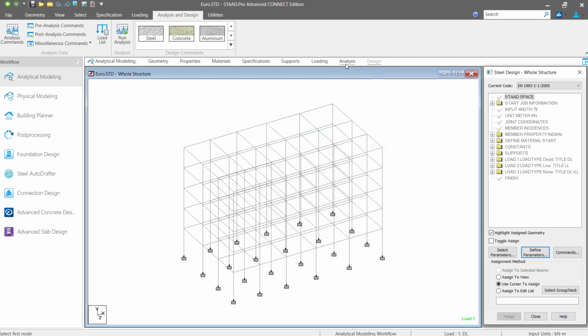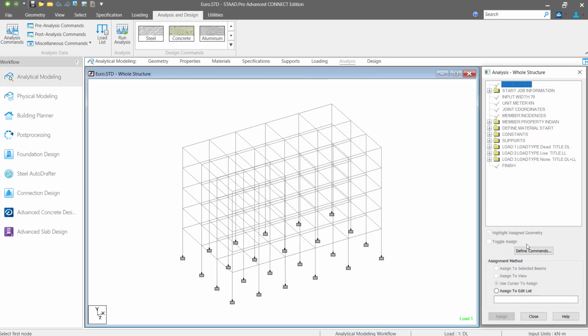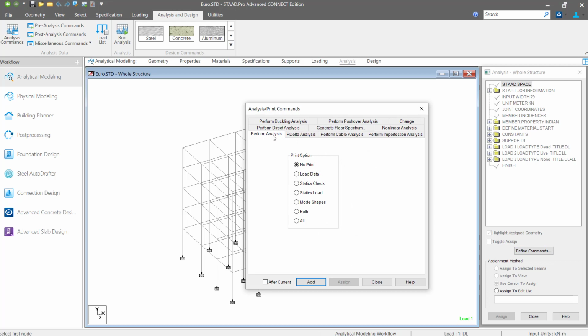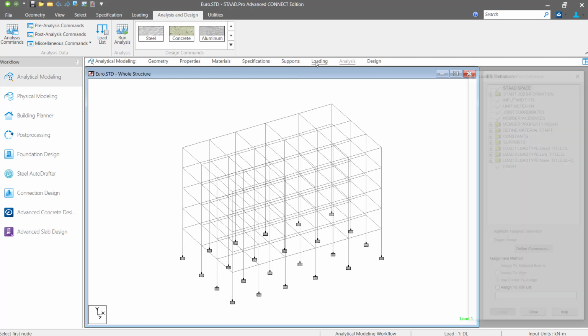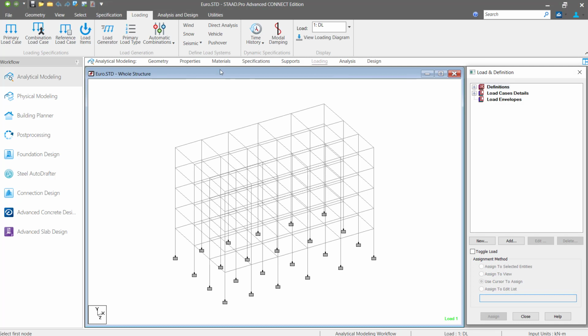But from the stability analysis point of view, first I have to determine what analysis method is required for this model, whether I should go for the first order elastic analysis or the second order analysis. Then we have to apply notional load in global X and Z direction to consider the initial sway imperfection. To finalize the analysis method, the global buckling factor for this structure is required.